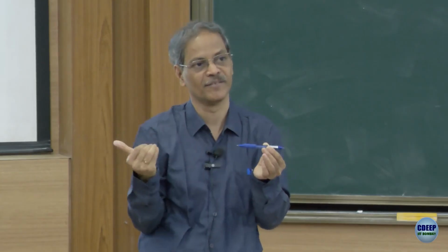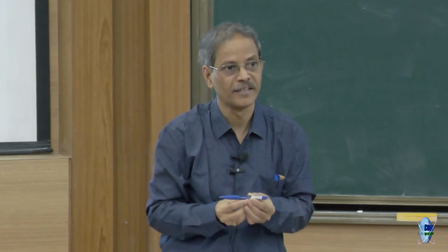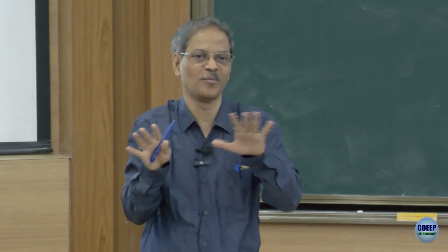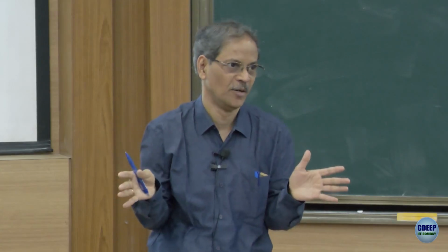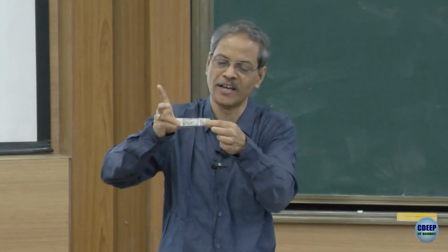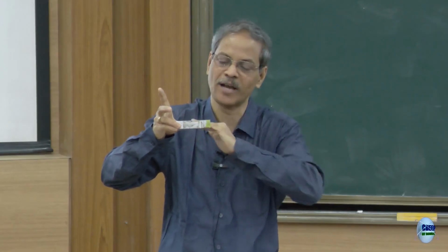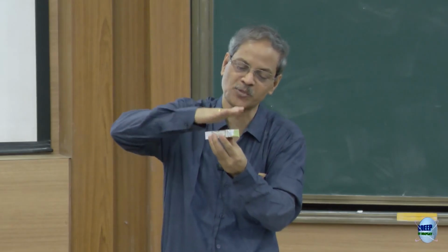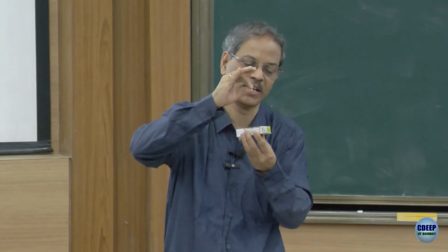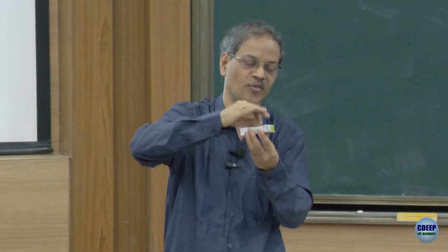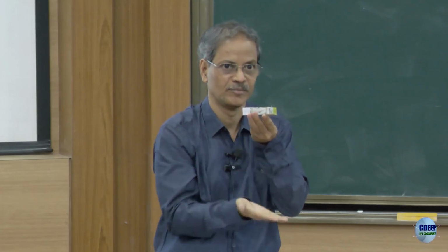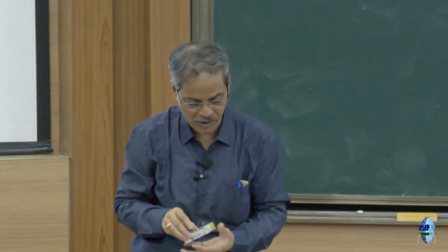Only along x remained. Here I am saying that along the r and theta plane, I can't make any reasonable assumption. I don't know how it would vary. But whatever is there in this plane seems to be okay along the thickness. So, therefore, I am knocking off thickness. I will consider only this plane for finite element modeling. And whatever results I find for deflection, strain, stresses or fluid velocities or whatever it is, I assume that it is applicable across the entire thickness. Okay. So, keep that perspective in mind.